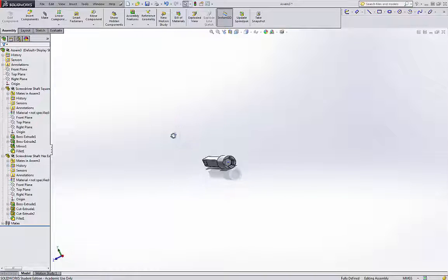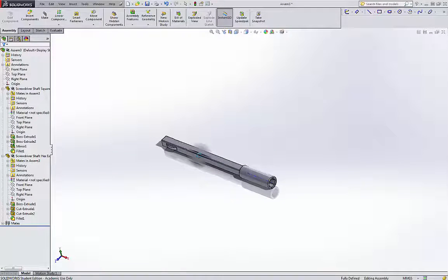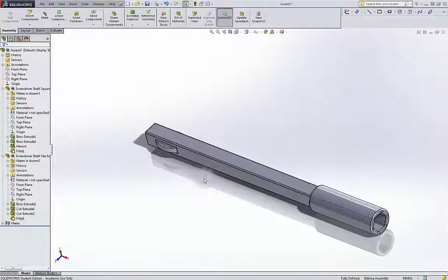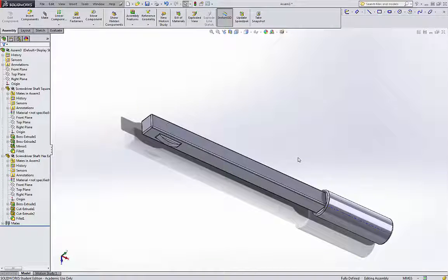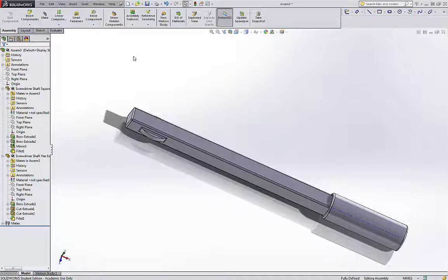Okay, so we're going to save this as an assembly, and then we're going to bring it in and create a new one. I see this as a part that you might have made at a contractor. So they may have sourced the metal, they may have made the hex part and then welded them together. We can put a weld on here actually. We can go to Assembly Features, Weld Bead,